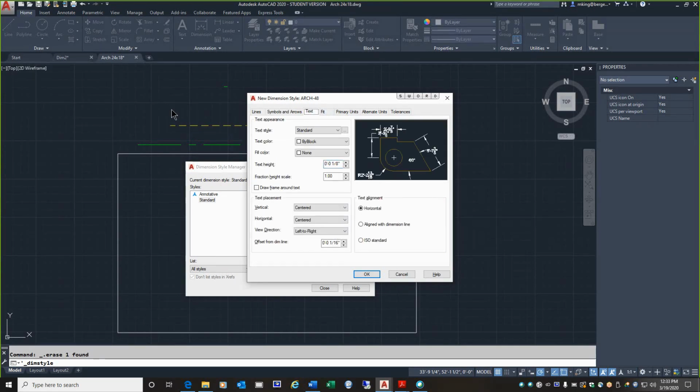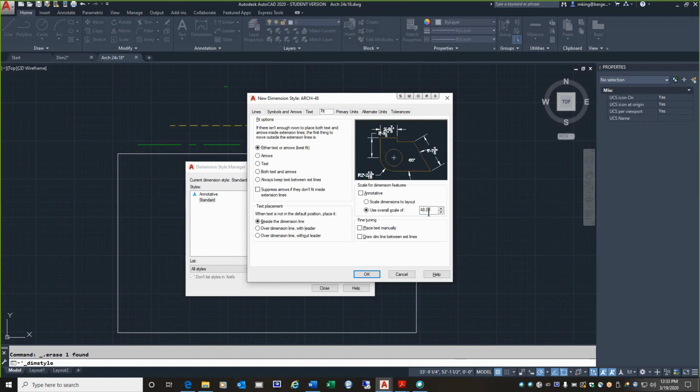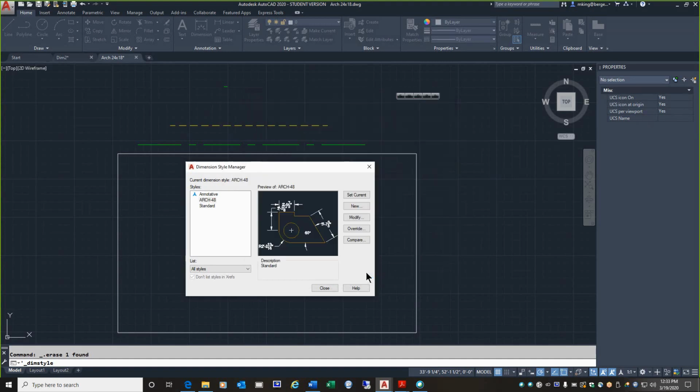Remember, in the drawing, when I created that dimension, you couldn't even see the number. If I multiplied the text height of that number by 48, it would be visible and it would be the correct text. That's what this value is doing for us. All right, so that was step 7A, 48. Now, these next couple of steps are going to get weird on you. Just follow the course, stay with me, and trust me. So, step 8 is to pick OK.